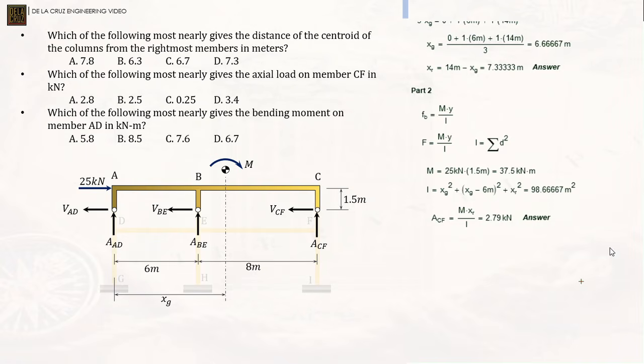Okay. To tell you guys, the solution here in the cantilever method using the bending stress formula is very easy, unlike doing the ratio and proportion, where you have to express the forces on each column in terms of one column so there is only one unknown. And could you make mistakes with the distances? It's still up to you. This is just an idea for you that we have an alternative solution there.